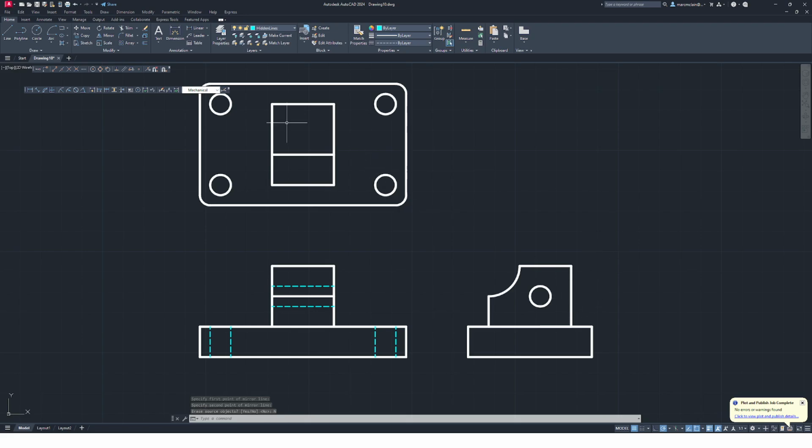All right, now, to get the hidden line up here is real simple. I'm just going to offset and pick the quadrant here and there, okay? That is this line. Now, I'm going to change it to a hidden line. And I'm going to copy 0.5. So here, 0.5. And there is our hidden lines. Okay, so all our hidden lines are in.